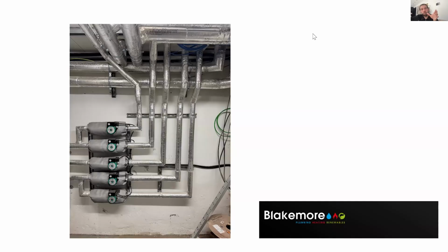Like I said, the heat loss was a little bit off. They had 44 kilowatts of ventilation and infiltration loss on there. So when we went back in, we put sensors in rooms. We took in solar gain, shading, wind direction. We got in a specialized heat loss contractor. We managed to get it down to just under 40 kilowatts, so we can provide the full heat load just through them. He's also got a full VRF set up, which he can bring in when it goes lower to help with that.